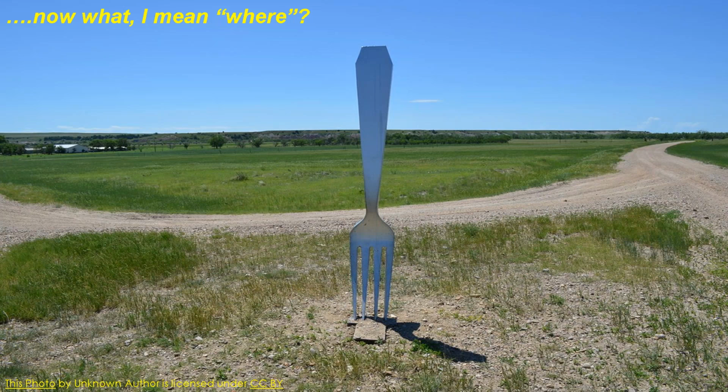So you got your first results. Where do you go? You know, we're at the proverbial fork in the road. First run results, we either refine the mesh and repost and reprocess and rerun that analysis, or we go build a prototype, see how that does, and go to manufacturing.